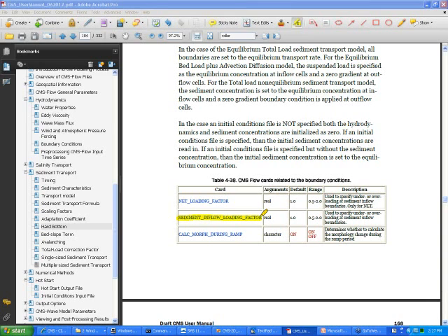Hawaii, areas where you have lots of coastal reefs. The reefs are basically a hard surface that don't have any sand on top of them, right? And so the transport capacity or potential in those areas is very small because it's limited by the availability of sediment. If you specify a boundary condition in an area that has a limited sediment supply, then you would want to reduce this loading factor, give it a smaller number. That's where you would want to apply that.